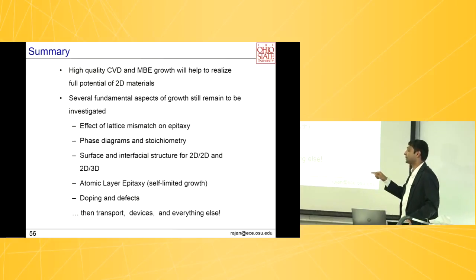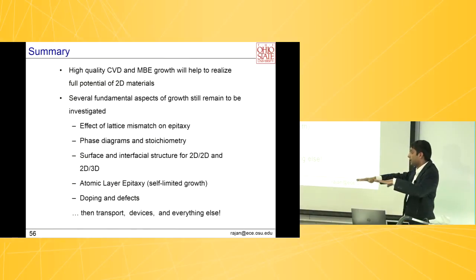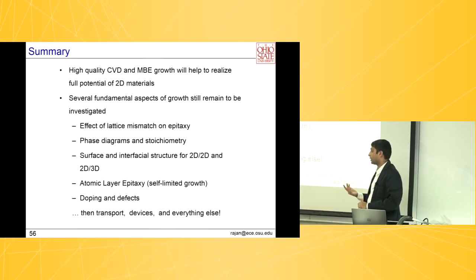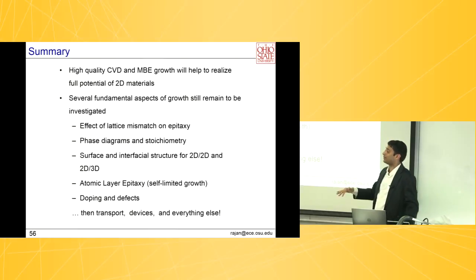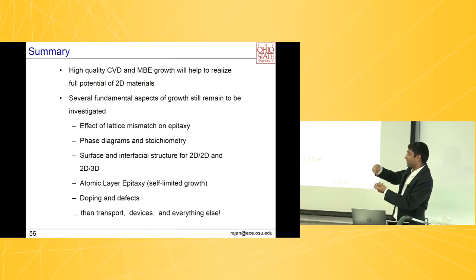If you have to have single crystal, you have to have something like what we did with the sapphire, where it is actually everywhere, but it's commensurate. People do this in 3-5 epitaxy. They grow commensurate kinds of structures. So that might work, but in the end it's best to be lattice matched. You want to find a lattice matched substrate so there's no problem with epitaxy, and the epitaxial relationship is very clear.